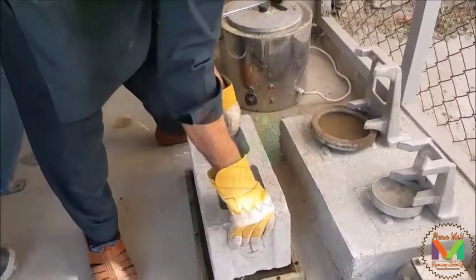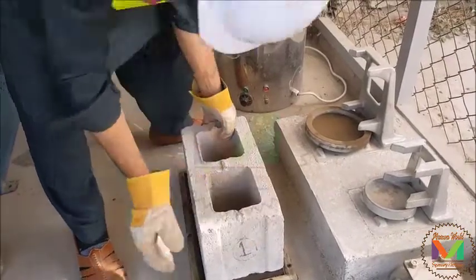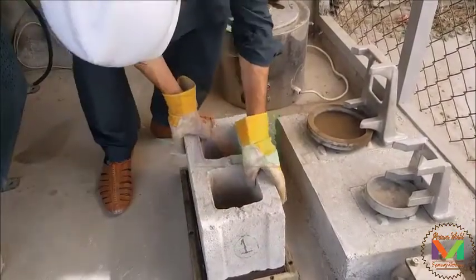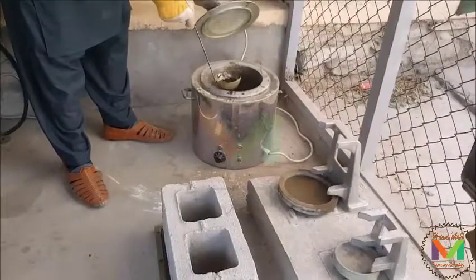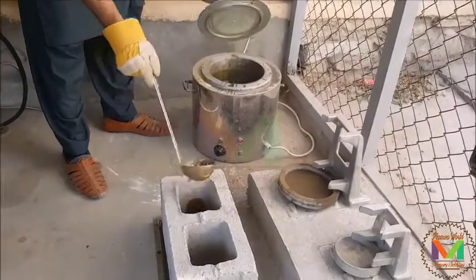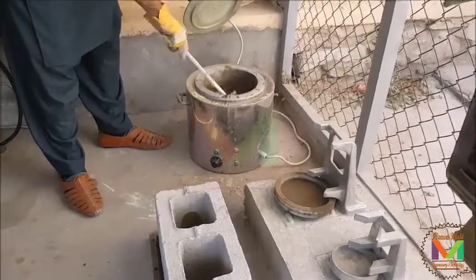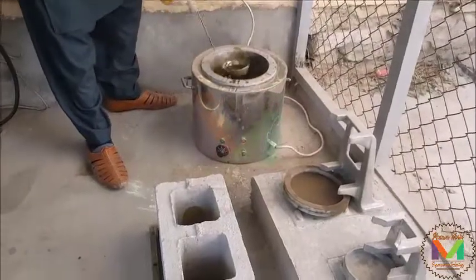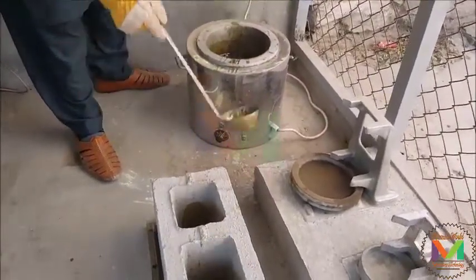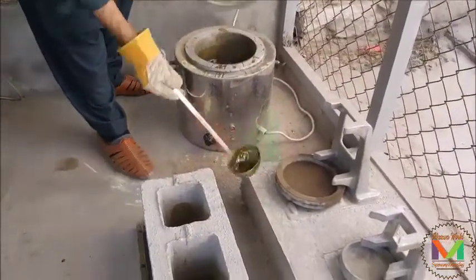Bring the surface of the specimen to cap quickly into contact with the liquid, holding the specimen so that its axis is at a right angle to the surface of the capping liquid, which is going to comply with the requirement of 7.4. As you can see, we are pouring some extra sulfur in it to fill the gaps.